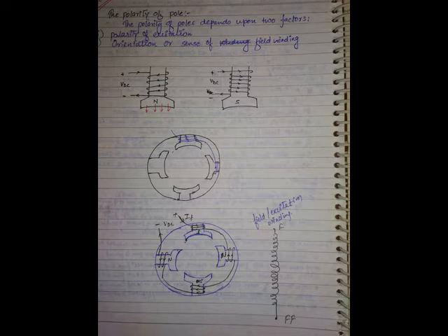By adding silicon to steel, which is also called electrotechnic steel or electrical steel, it is not destroying magnetic properties, but it is reducing conductivity to eddy currents. As well as in the losses topic, we will discuss this thing.